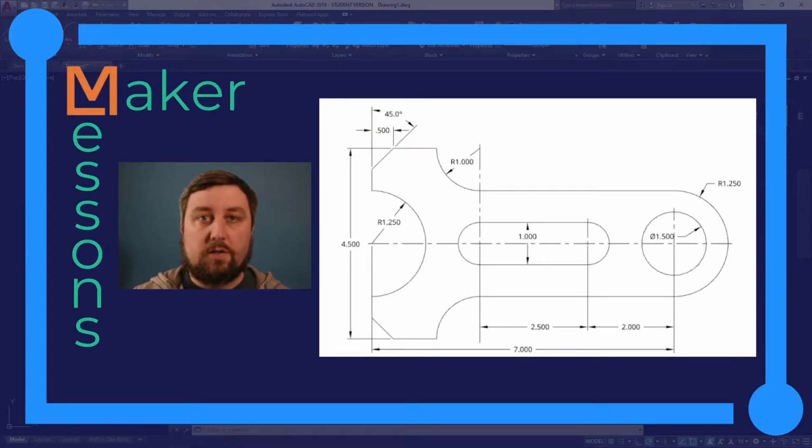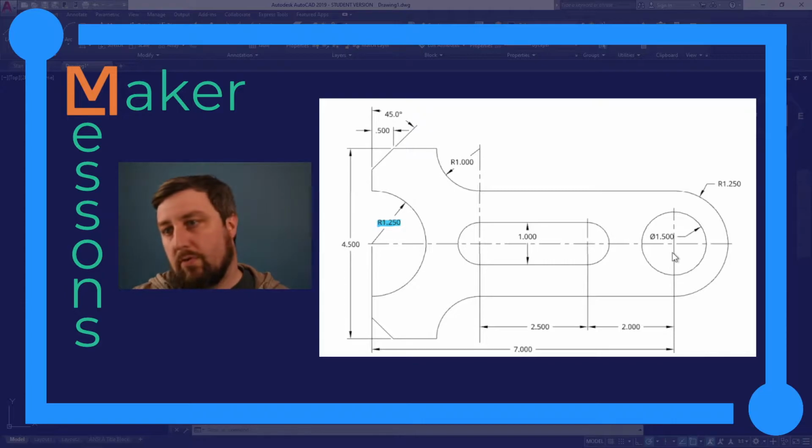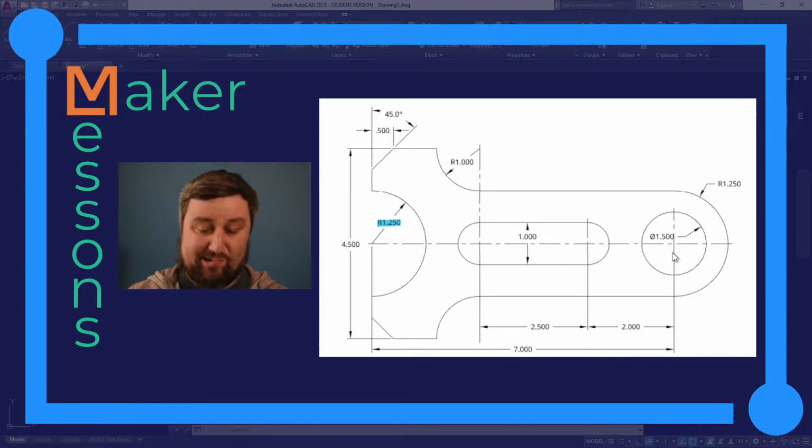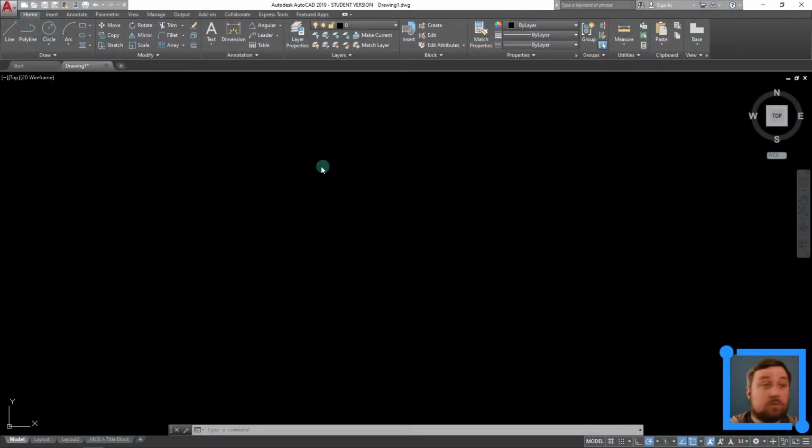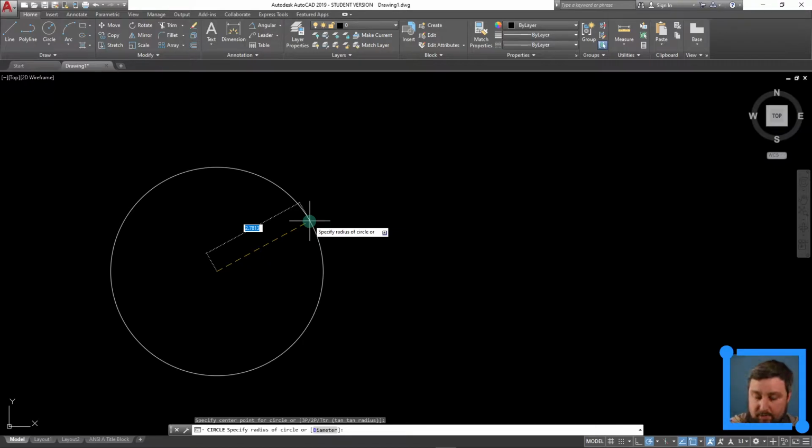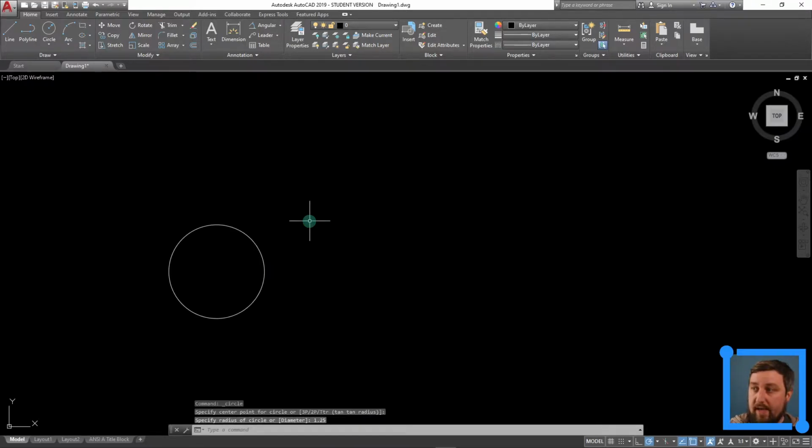All right, we've got the adjusting arm single view drawing up next. I'm going to start with this end down here and do a circle at one end, then move over to the right and do all of my other circles. So my first circle, words are hard, is a radius circle. Making sure I'm choosing a radius, pull this out. My radius is 1.25, enter.